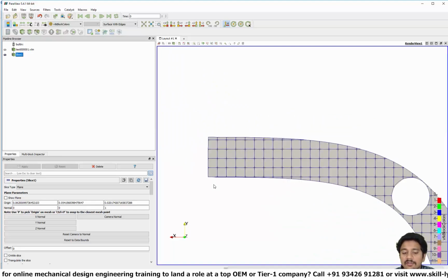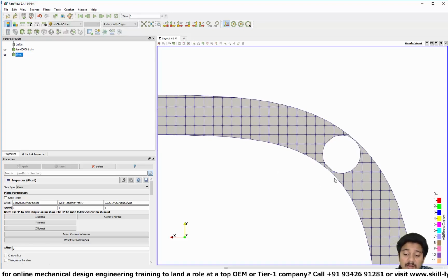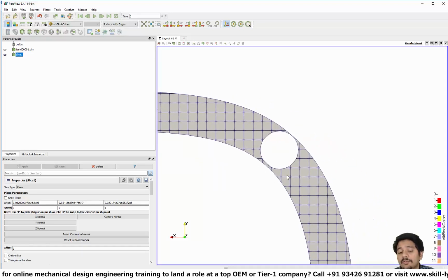All right, so here what we can think about doing is, whenever you have a pipe, it's good to have at least a few cells across a diameter. So here we have 2, 3, 4, and then there is a cell here which is cut in approximately half, right? So this leads to something called a cell pair. We are not going to be talking about cell pairs right now, but you can just assume that it's a separate cell. So we have 1, 2, 3, 4, and 5 cells, which is okay. It's a decent start. It can be better, but the main problem is this guy.